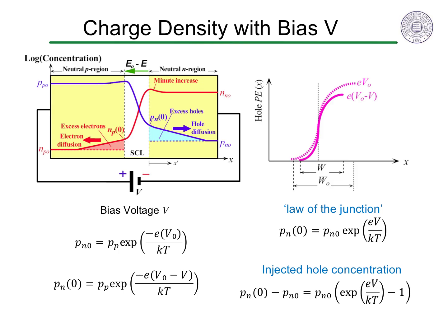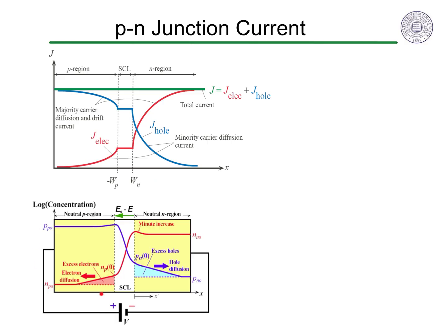We can expect that this is due to charge carrier diffusion and that the decrease should be an exponential decay where the characteristic length is the diffusion length of the minority carrier. For the device, we want to know the total electrical current due to the bias voltage. The total current is the sum of the electron and hole, diffusion, and drift currents.